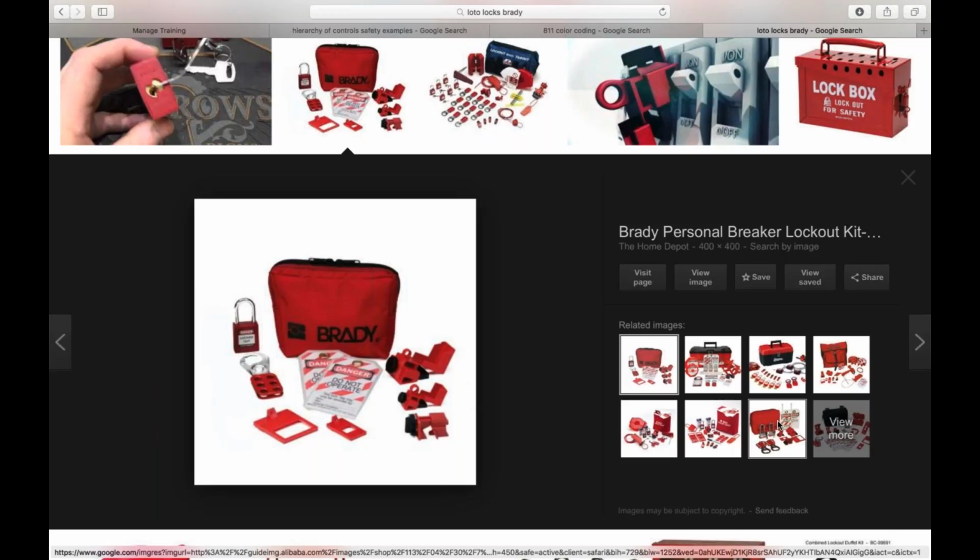And then any training requirements, right? Respirator training requirements. If you go back to last week's session and then our confined space session again, we talked a lot about air purifying versus air supplied respirators. So we'll make sure everybody's up to speed on that as well. And then remember, different cartridge colors mean different gases or particulates that we're protected from with air purifying respirators.